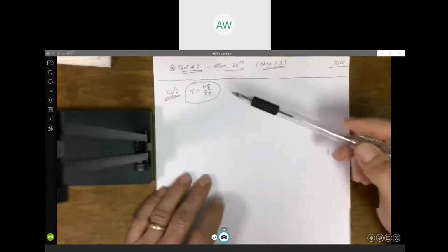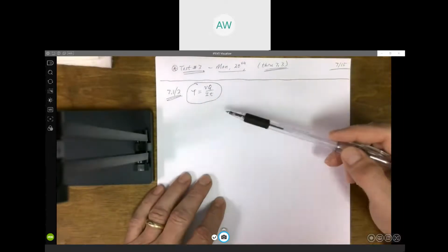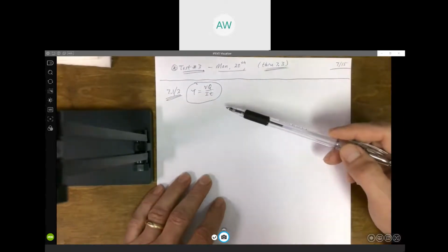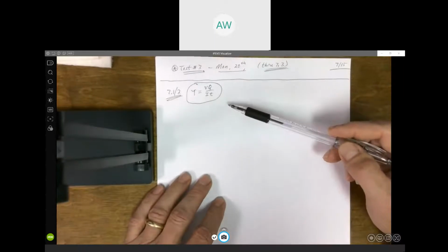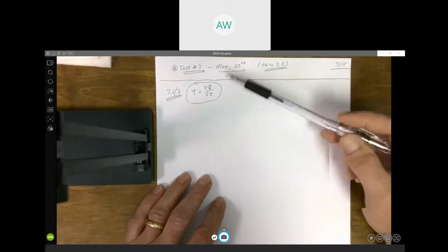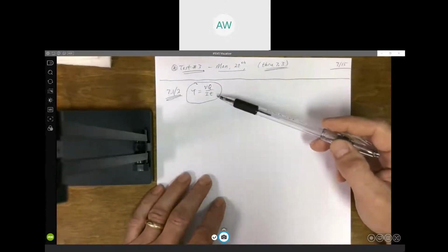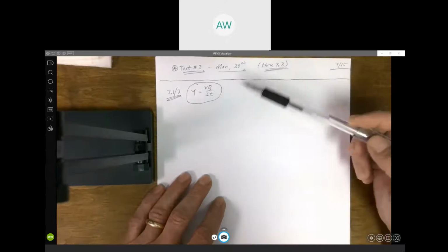Again, this would be the shear stress located at the position some distance y prime away from the neutral axis. You're looking at the cross section. V is the internal transverse shear force acting on that particular cross section.